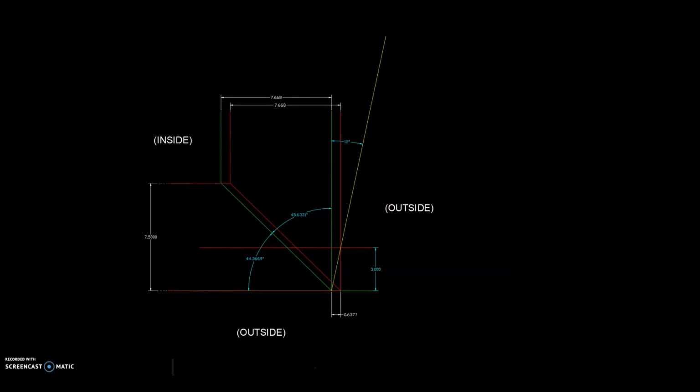Now I'm going to be the observer and position myself right here in line with the miter lines of the footprints. Once I do that, I will see those as points. The green point on the bottom footprint, and 3 inches higher and a little bit to the right, the red point on the top footprint. And the moment you have that in front of you, you can make a line between the points, and that will be your tilt.